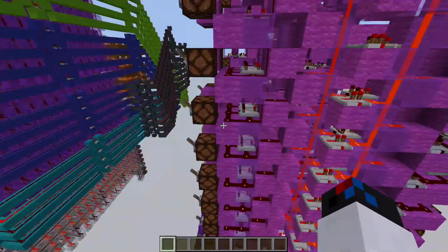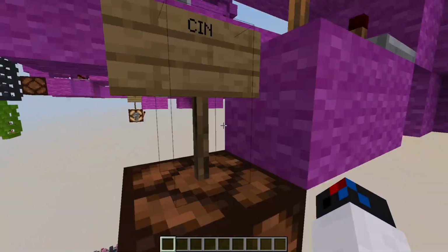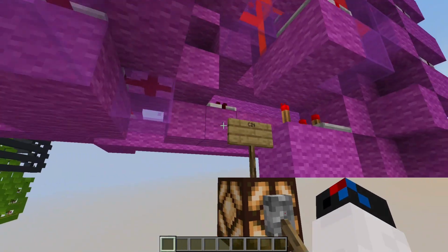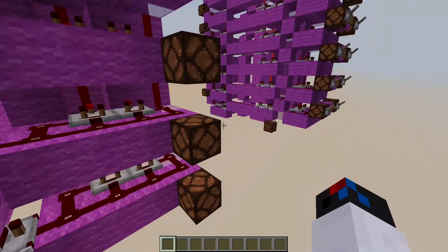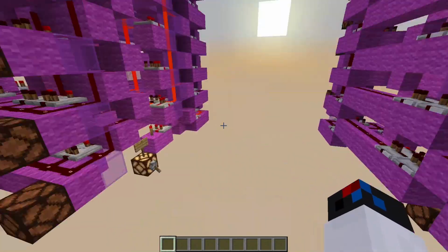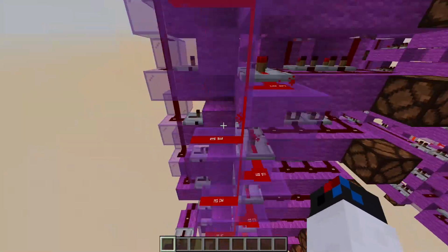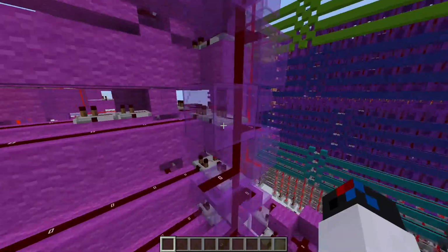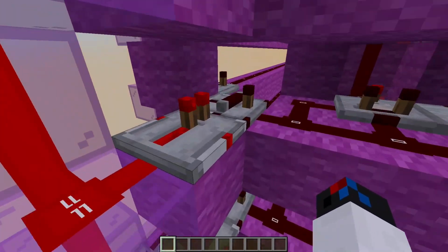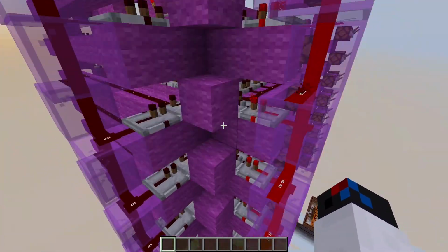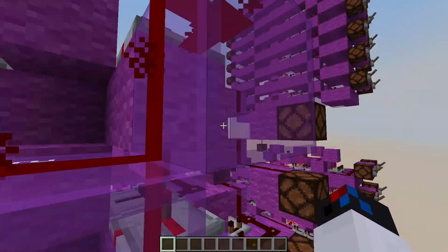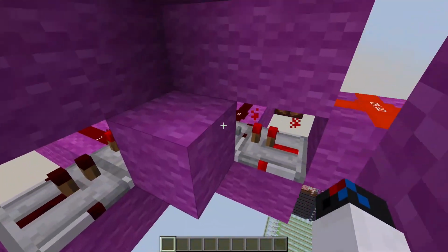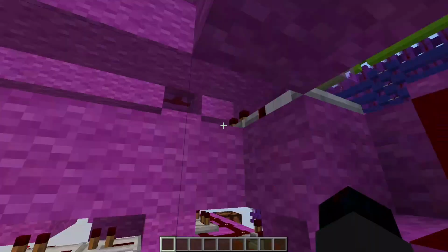And then in order to add 1 is also very simple. You just activate this carry. As you can see, I just activate this carry, so now the number will always be incremented by 1. So of course you have to wrap the output back to the input, and between the output and the input there will be a register, and this register is going to store the current number.